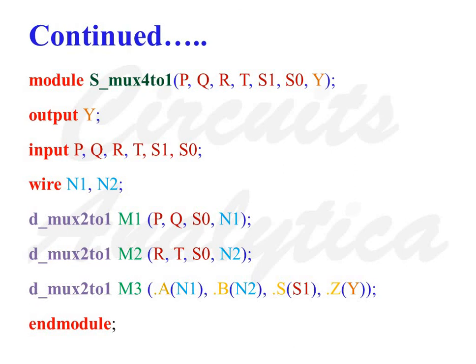So there are two different ways to associate a sub-circuit with a circuit: named association and positional association. The first two instantiations, the instances M1 and M2, are examples of positional association, while the third instance M3 is an example of named association.